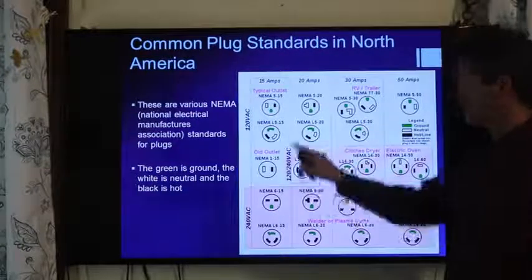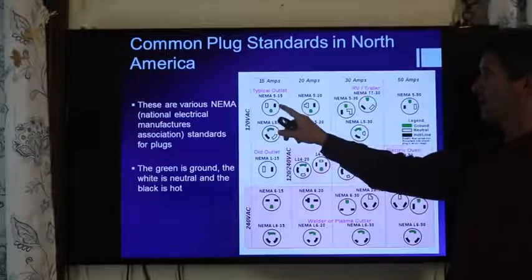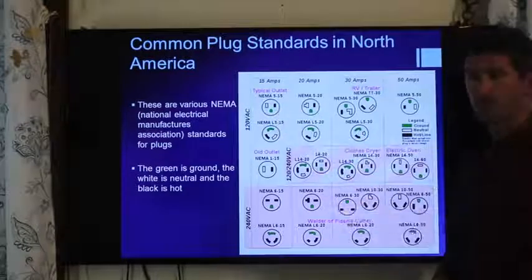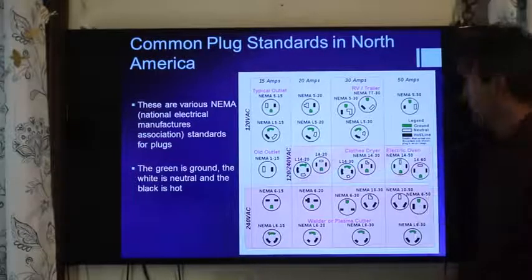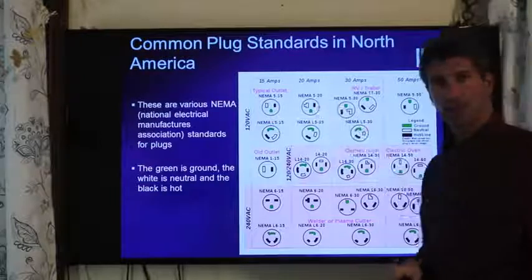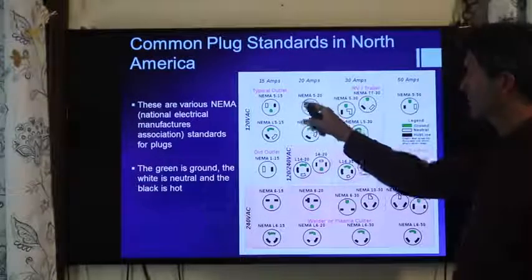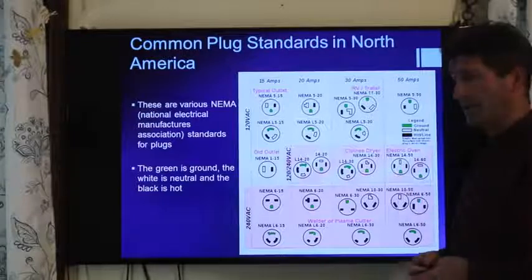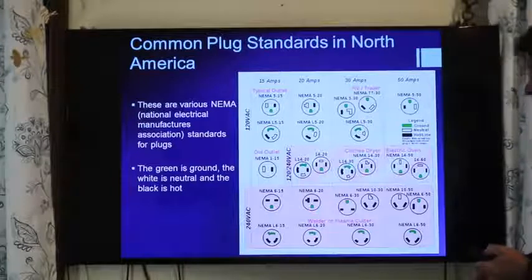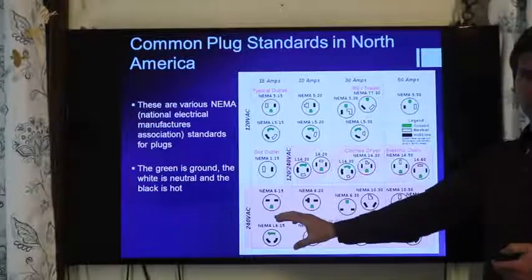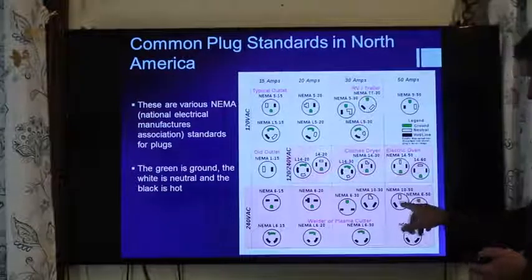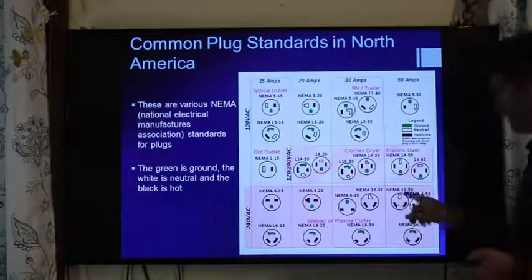Probably the most typical outlet looks something like this, which is polarized. You've got the neutral, which is the bigger, the hot, which is the smaller, plus a third prong for the ground. For 20 amps, you'll see sometimes the neutral will have this little prong that goes out this way, that indicates that it can take higher currents than most circuits. And again, for 240 volts, you also have different, here's the one that we just looked at, where you have two hots and one neutral.